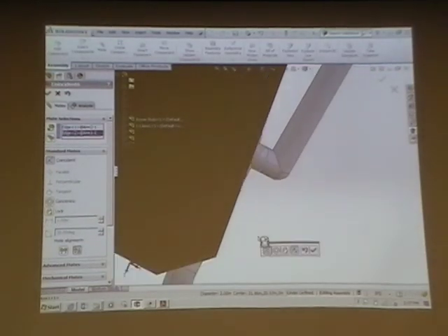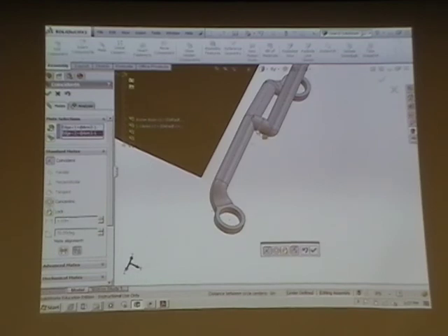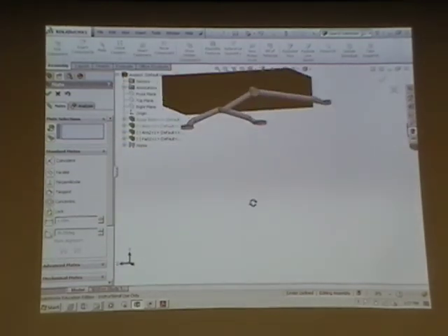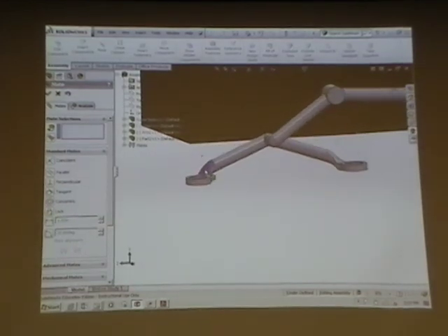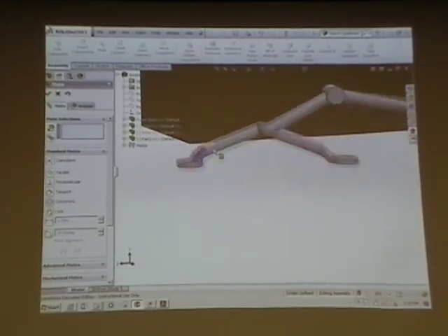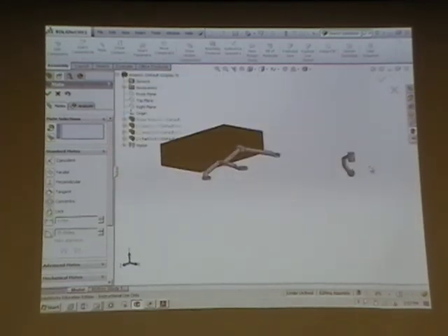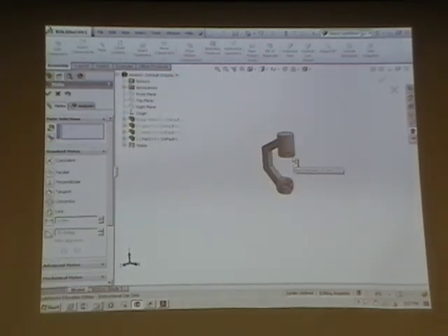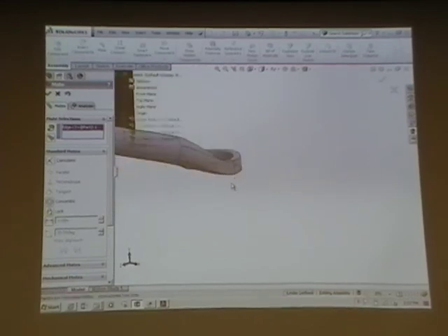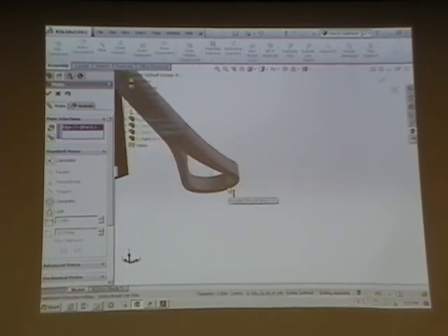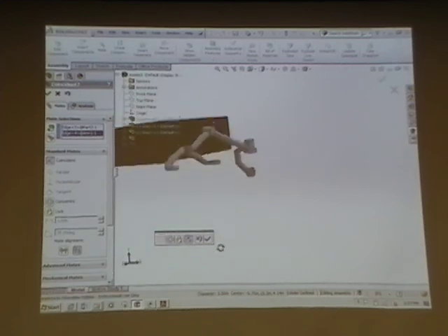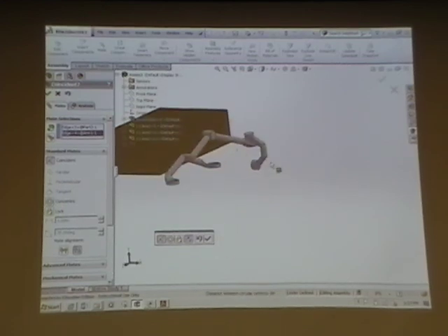Okay, and that brings it down into position. Those are aligned correctly. So now this arm is also free to rotate, but it's going to stay attached to Arm 1. Now let's do the same thing with this arm. I'll take that lower circular edge and mate it to that lower circular edge of that receptacle. Okay, and it's free to pivot.